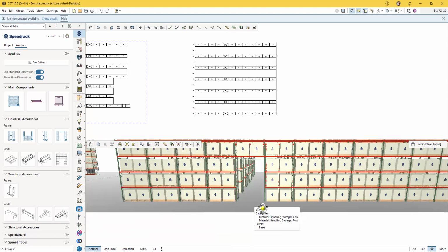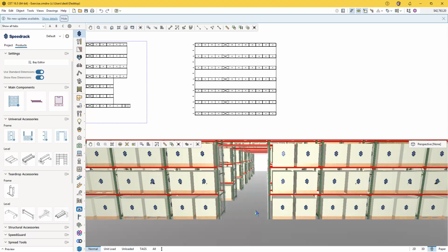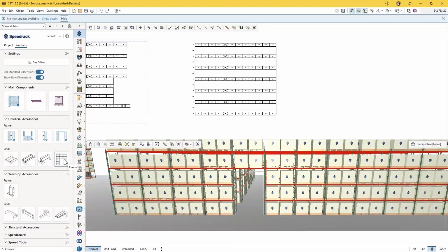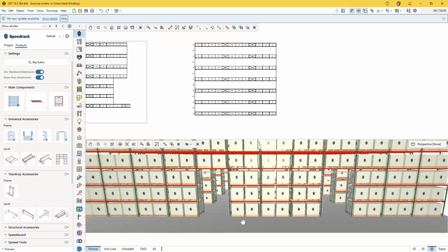This is how it's intended to work here. Okay, so you can see a nice, beautiful tunnel happening. There we are. So again, I just use that tunnel tool. I decide where I want to place that tunnel, give it the specified height, and a left click, and my tunnel will be placed.